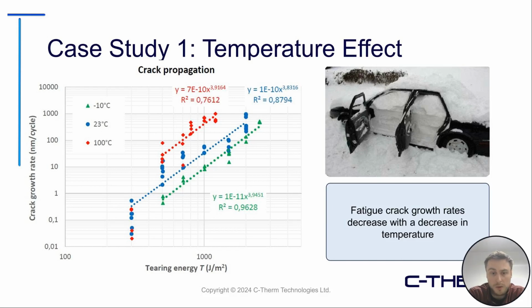This can be the big issue with tires in terms of sidewall blowout. If they heat up, they get to an unexpected hot temperature, the resistance to cracks is greatly reduced, causing the sidewall to blow out, which is a serious issue for tires. But we can also see, for lower temperatures, that the crack growth resistance is greatly reduced too. So just to show you the science that's going into your tires there, considering multiple different environments and